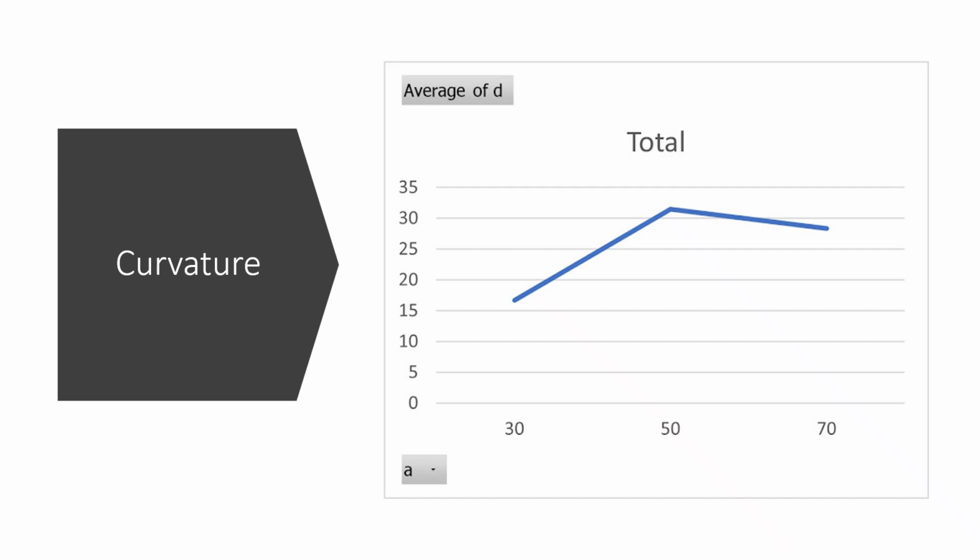Plotting distance as a function of angle, we see that the central point is out of line with the extremes. The relationship between distance and angle is not linear. This invalidates our linear model. We will try a quadratic model with response surface design of experiments.